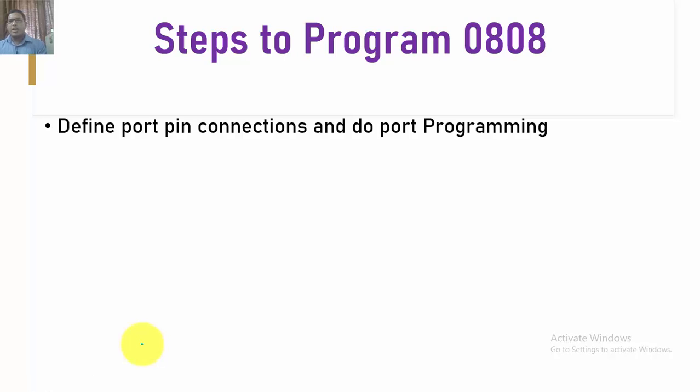No doubt we have to take into consideration this, that is first the input channel, then address line, then the address latch enable signal, followed by start of conversion, then end of conversion, and at last the data lines, right? Data lines, these are associated with the ADC0808. So no doubt the input signal is taken from a sensor, so no such big pin configuration or port programming is required here.